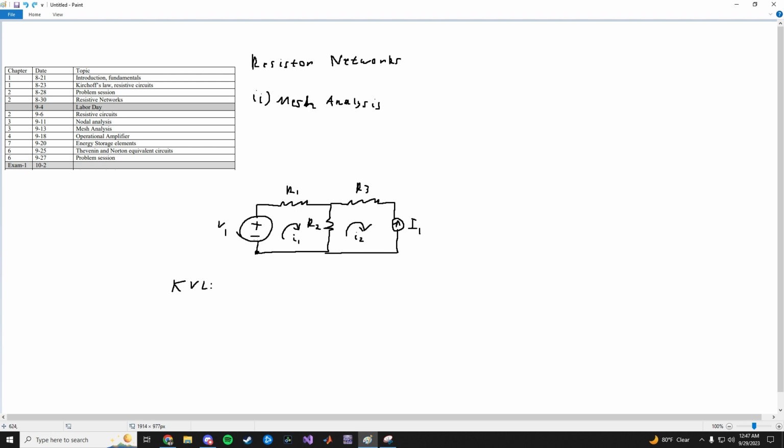So for sources like this voltage source, you start with a minus, because it's going up into the minus, so minus V1, plus, and then by convention, for mesh currents, you'd always say the current going from one terminal to the other, it always enters the positive and then out the negative. So this would go, by convention, the arrow would go into the positive and out the negative.